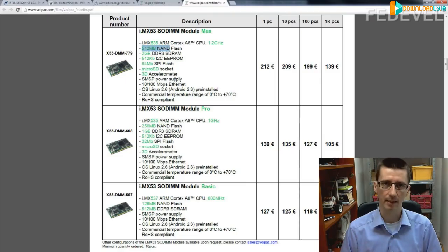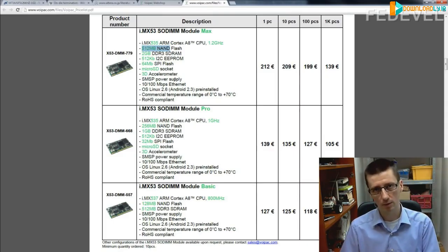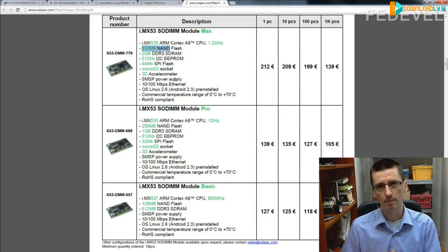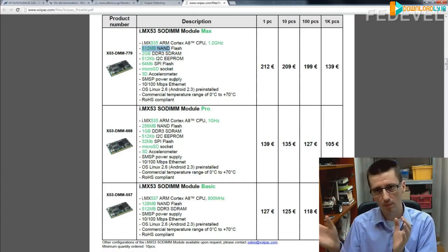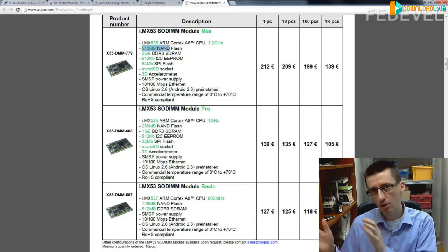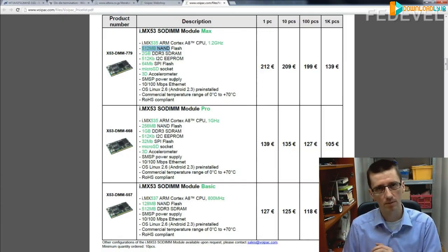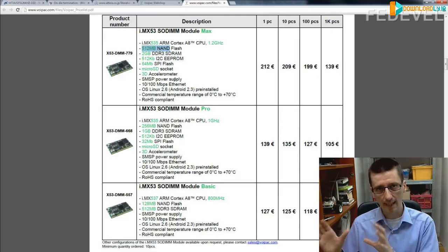generate the BOMs again. And it's not only BOMs, because you have to generate 3 BOMs, you have to generate also 3 different documents for a company which assembles the board. 3 different assembly drawings, 3 different pick and place files. And just doing all this component management from the BOMs and generating all the documents may take much longer than actually doing the changes. It actually takes quite a lot of time.